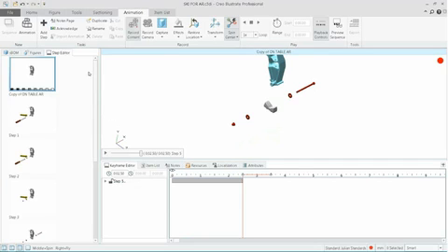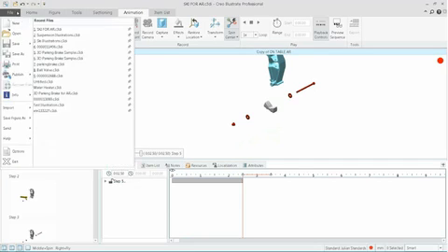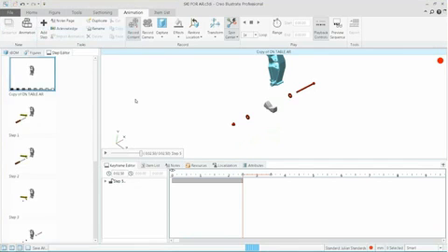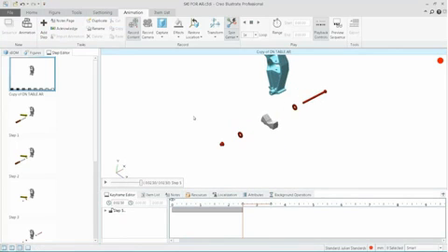Well, with Creo Illustrate 5.0, using the direct connection, I can simply choose File and Save. That is actually going to save and upload this illustration, both animations, to my Windchill environment, check them in, and I'll now have those objects managed in the system. Any type of CAD changes that might occur within Windchill, we'll be able to propagate all those changes back down to my animations that I've built within Creo Illustrate. And this concludes the first portion of our demonstration.